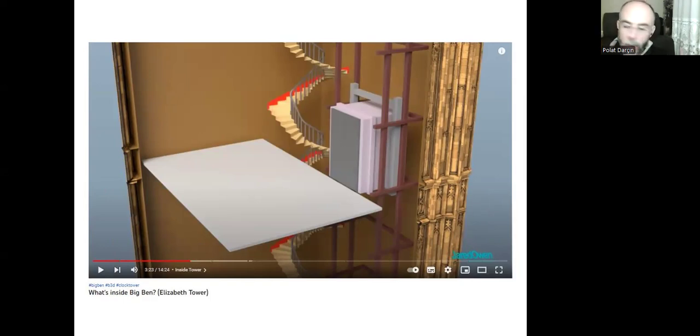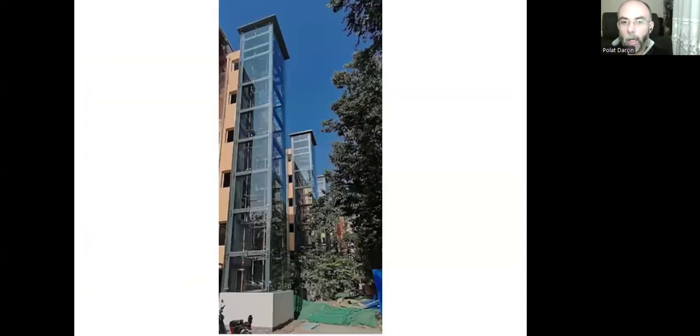We don't need to create reinforced concrete columns or shear walls or anything else for the elevator to carry its loads. We can design a very simple steel or timber structure and connect it with the main structural components of the building, and that's it. That's the thing that will carry the elevator.